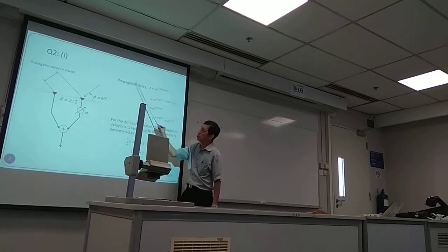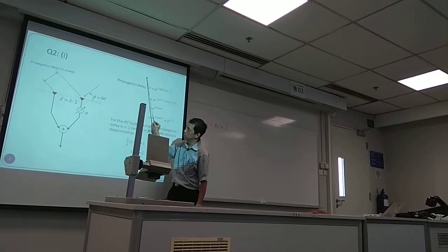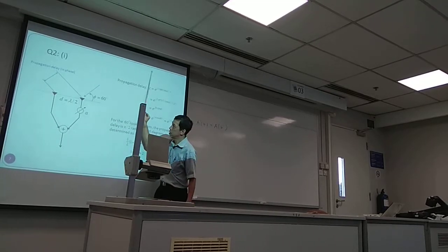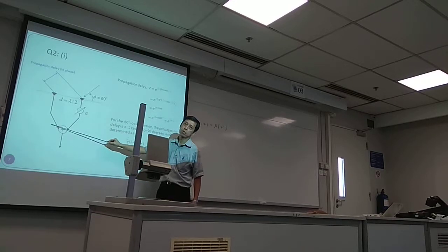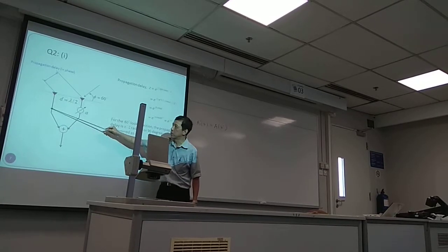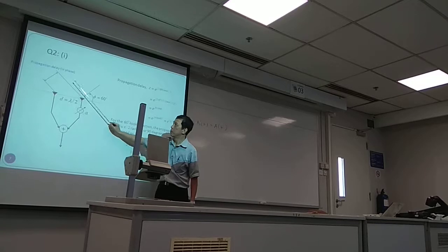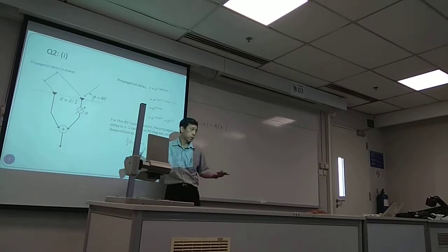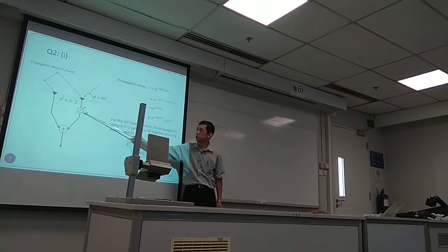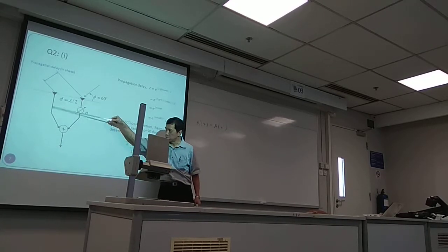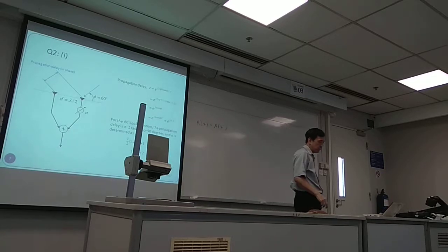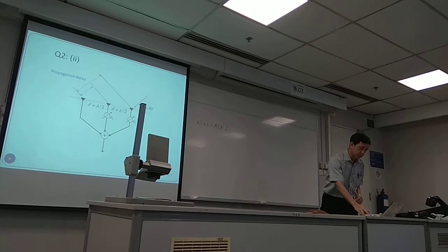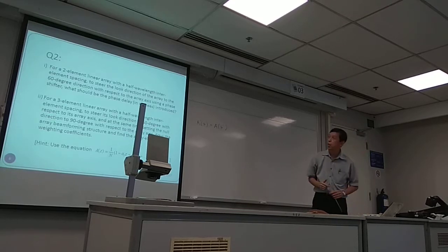So therefore, the overall response for this channel, the phase shift will be 0 degree, and as for the subsequent channel, again 0 degree. You see, the path here give you no phase delay, right? But the physical space give you 90 degree delay or phase shift. So therefore, the element here compensated for the delay over there, and you end up with two signals being in phase when they are summed. Okay, so that gives you the solution for part 1.